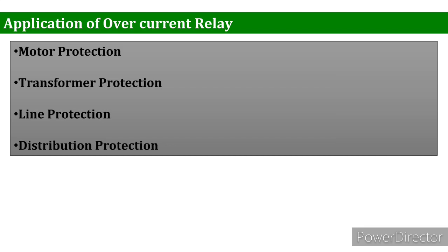If we talk about line protection, on some transmission lines where the cost of distance relaying cannot be justified, we can use it, along with primary ground fault protection on most of the transmission lines where distance relays are used for phase fault. You can also say it is used for ground backup protection on most lines having pilot relaying for the primary protection.